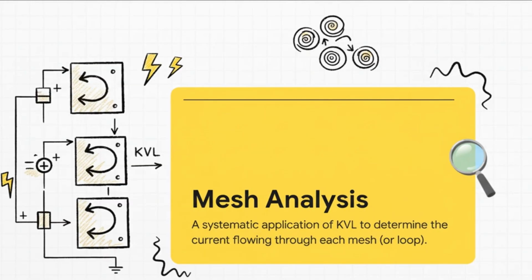Now, the natural counterpart to nodal analysis is something called mesh analysis. If nodal was all about KCL and nodes, you can probably guess that mesh is all about KVL and loops. With this method, we define a current for each little window pane or mesh in the circuit. By applying Kirchhoff's voltage law to each one of those loops, we can solve for all the mesh currents directly.